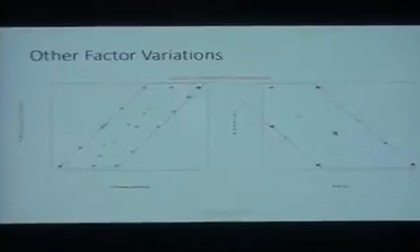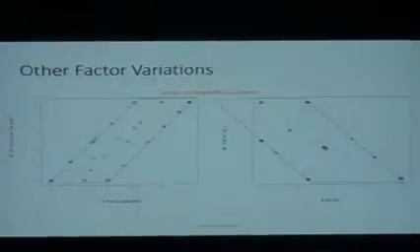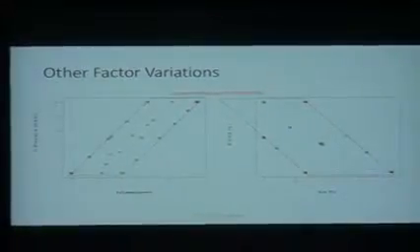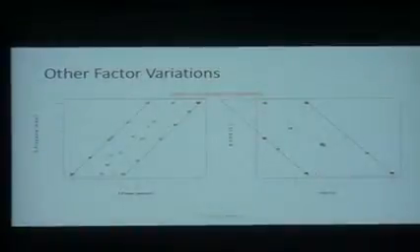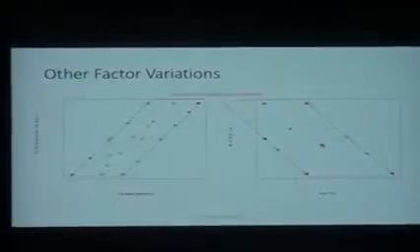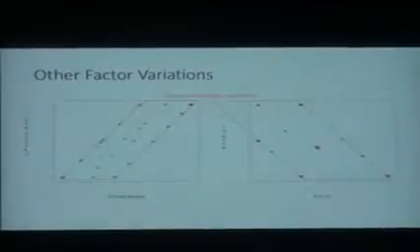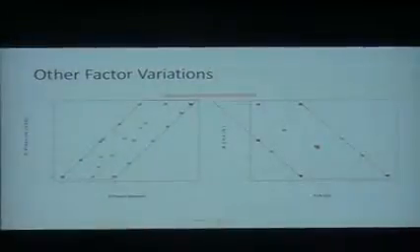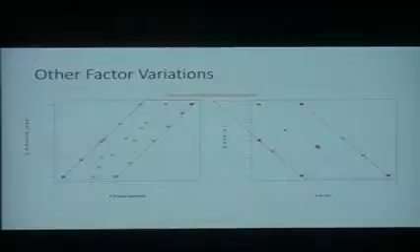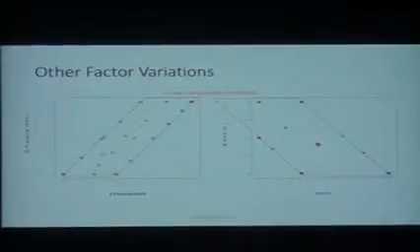You could also vary other factors, and you could put constraints on your system. So in our case, we don't want the microwave power to be too high for a given pressure, but that maximum power changes as pressure increases. So as pressure increases, we can accommodate more plasma power. There's better cooling from the gas in the system. So you end up seeing these diagonal boundaries in your design space. So you could actually design constraints into your system so that you're not breaking things as you go. That's also important for the experimentalist.